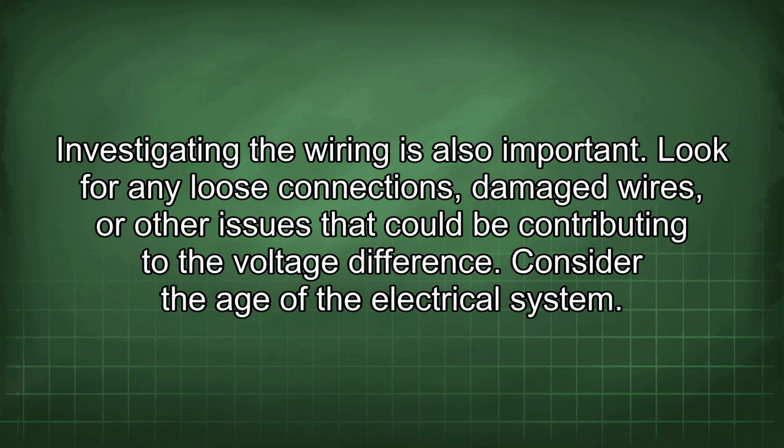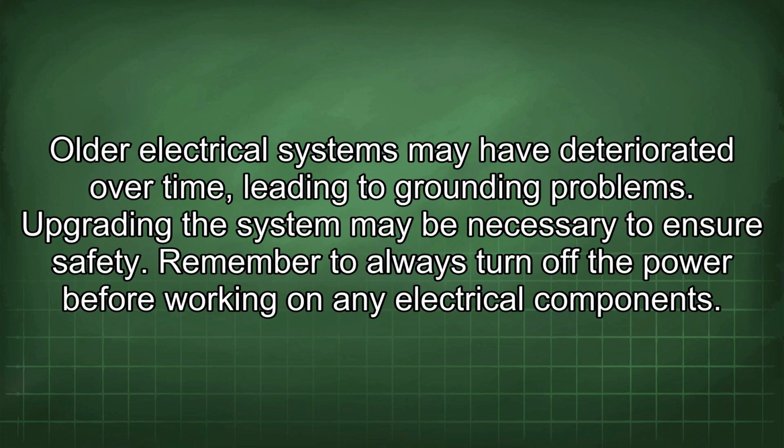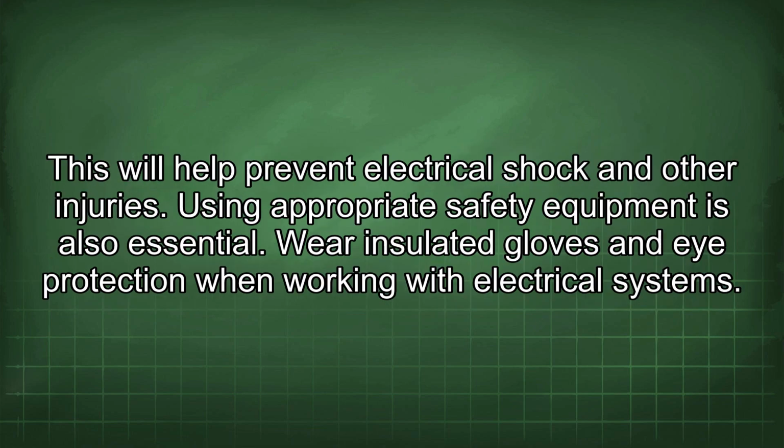Consider the age of the electrical system. Older electrical systems may have deteriorated over time, leading to grounding problems. Upgrading the system may be necessary to ensure safety. Remember to always turn off the power before working on any electrical components. This will help prevent electrical shock and other injuries.